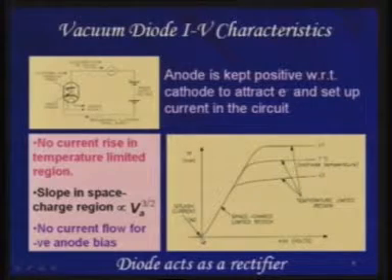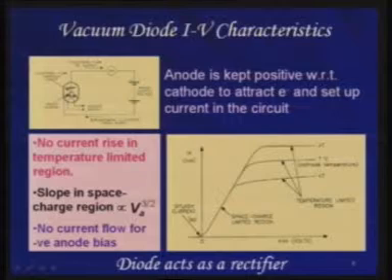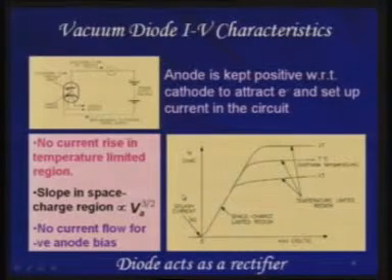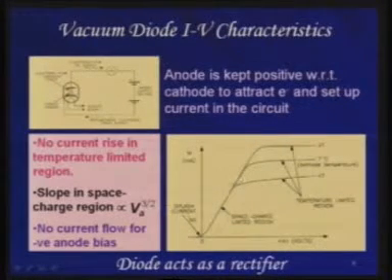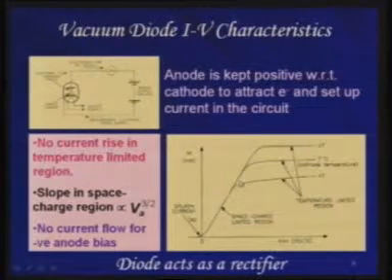This is the current of the few electrons which were emitted and, without even any application of anode voltage, try to reach the anode, and it is called a splash current. It is a very small current, but as we start increasing the anode voltage, we get more and more electrons attracted, so that we get a higher and higher current.